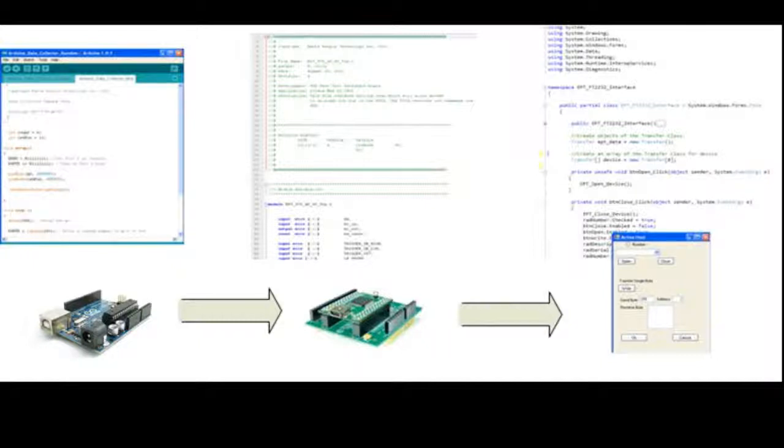The Arduino will generate a 10-bit digitized word for each channel and then transmit that word to the CPLD using the write enable, address, and data pins. The CPLD transmits each 10-bit word to the PC using an active transfer in term and a one-hot state machine. The DLL reads the 10-bit word into local memory, then calls a callback function. Each 10-bit value is finally collected and displayed in a text box in the Visual C# code.